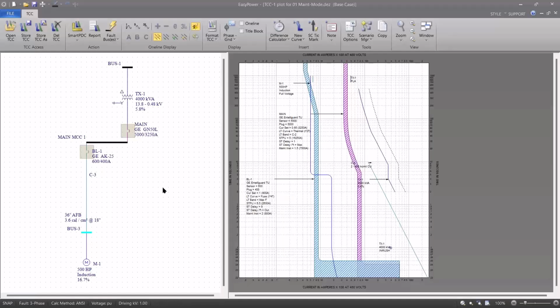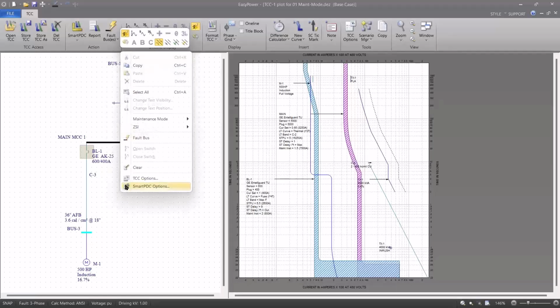So again, this information, being the incident energy when we have maintenance mode in place, has no business being on the label, according to me. My point is, there may be people that are not well aware of not only a maintenance mode effect, but the arc flash in general, that may take that lack of knowledge and try to apply maintenance mode to work on a hot bus and get themselves in trouble. So where the information belongs is in the hot work permit,